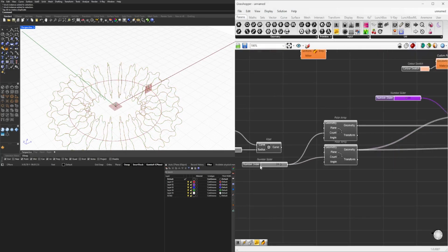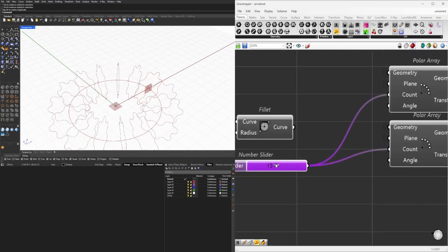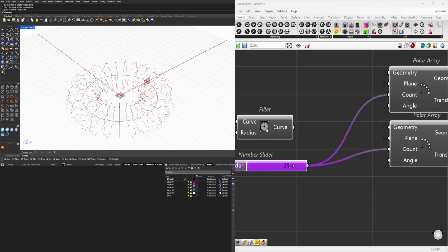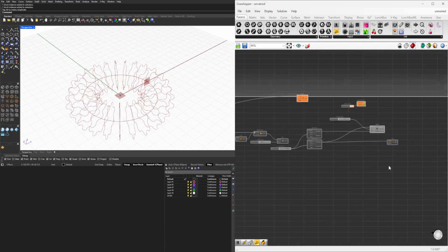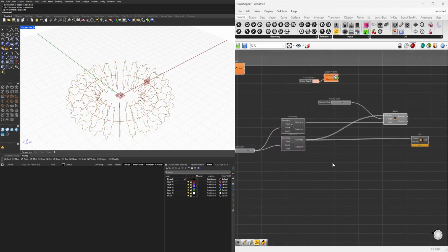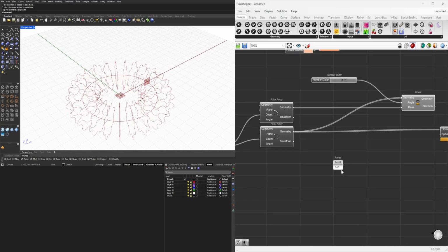We know how many objects we have because we have 24 arrays, which means that we have to create 24 different rotations that increase by a specific number. Now, if that's a little confusing, let me show you how this kind of works. First thing is, when you rotate something, we are rotating it a specific amount. So if we want to rotate it once, that's based off of 360 degrees. So bring in a panel with 360 because that's how much we're trying to rotate.